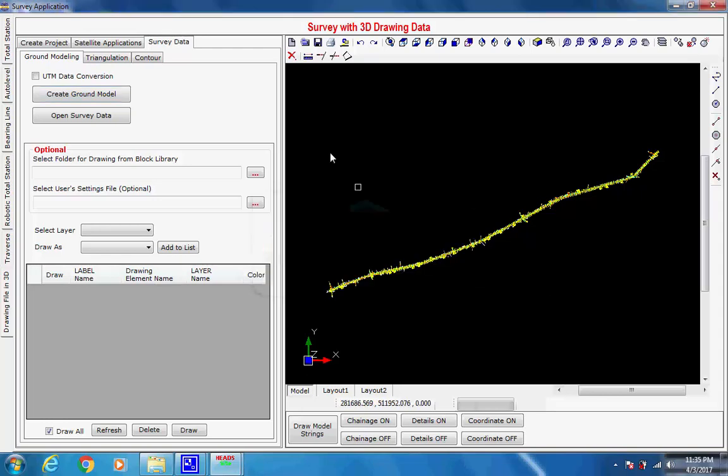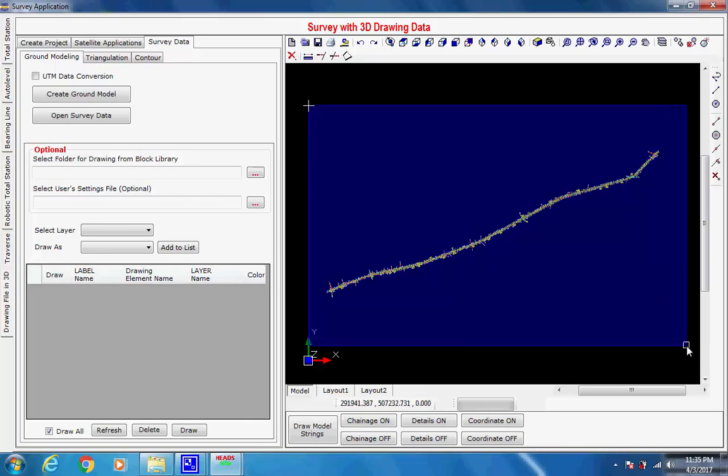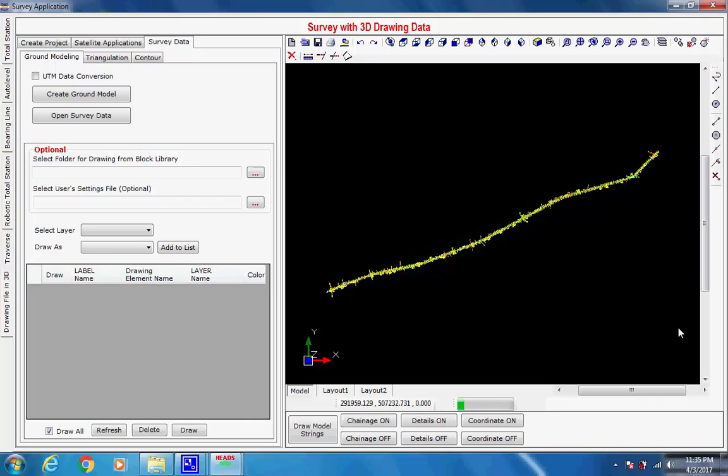Click left mouse button at diagonally opposite corners of the survey drawing. Next, click the right mouse button to complete the selection of the entire drawing. The model with string labels taking from the layer names of the drawing is created and saved in the model files. The message comes. Click on button OK.